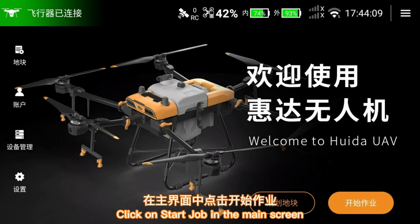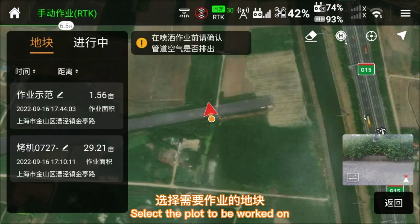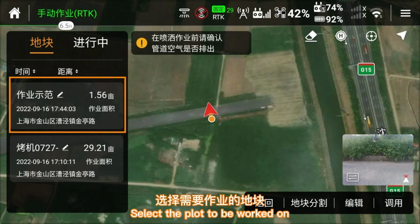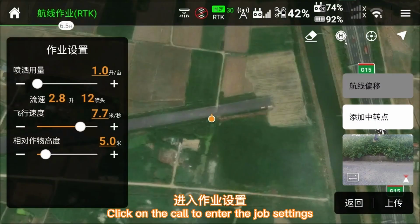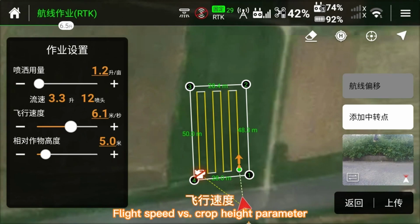Click on Start Job in the main screen. Click on Call Plots. Select the plot to be worked on. Click on the call to enter the job settings. Set the spraying rate, flight speed and crop height parameter.